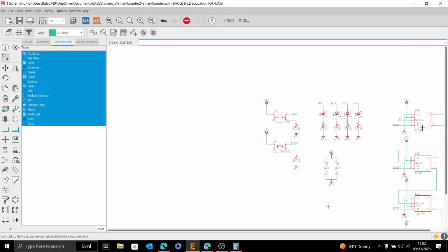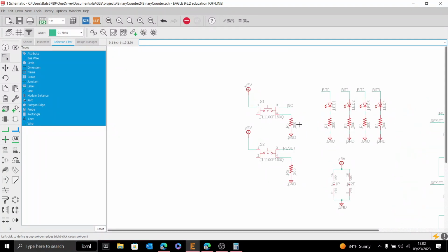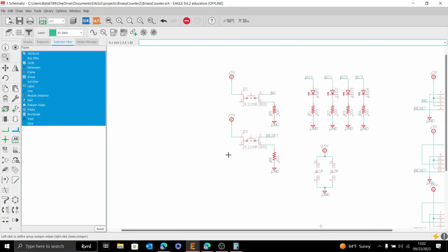And it worked. Why didn't I debounce before? Probably because it was midnight. I mean, I already shorted out these buttons, so clearly I wasn't thinking at the time. But ideally, if you're going to use a button with a sensitive input, you do want to debounce it. I'm not going to debounce the reset, because that is a simple, if I'm high, I set everything clear. I don't really care about debouncing it, so we're going to cheap out on that.